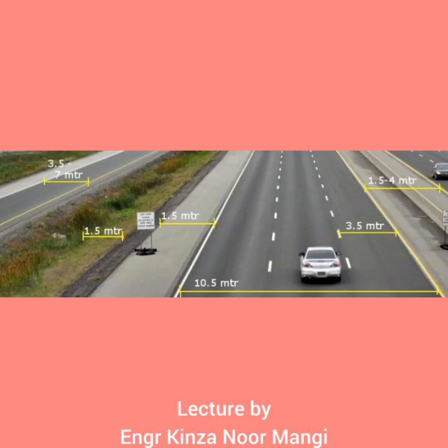Width of the carriageway. Width of carriageway or the width of the pavement depends on the width of traffic lane and number of lanes. Width of the traffic lane depends upon width of the vehicle and the clearance. The side clearance improves operating speed and safety. The maximum permissible width of the vehicle is 2.44 meter and desirable side clearance for single lane traffic is 0.68 meter.